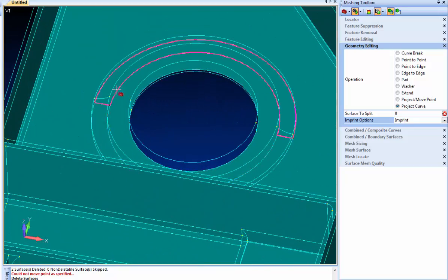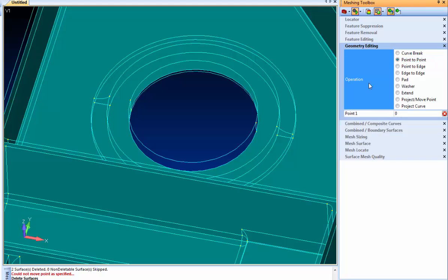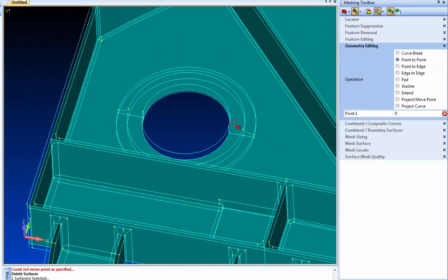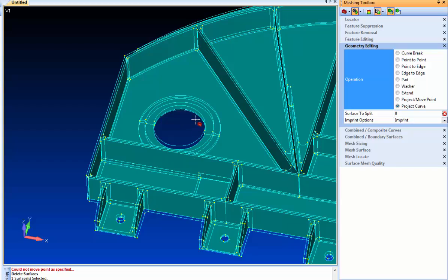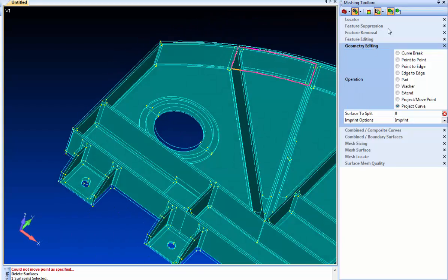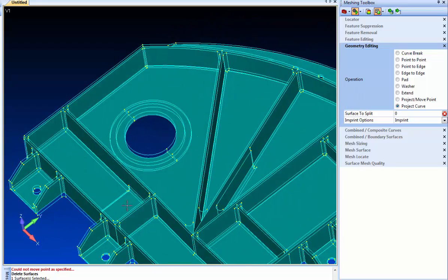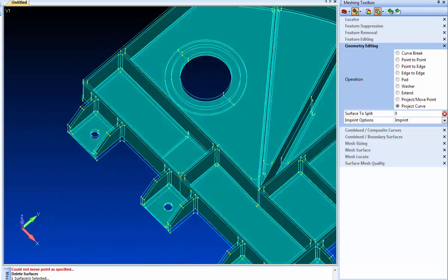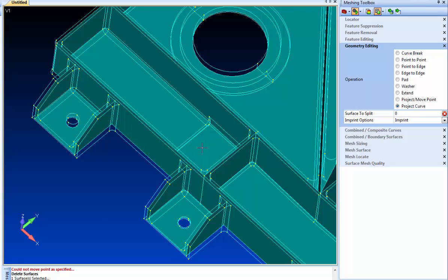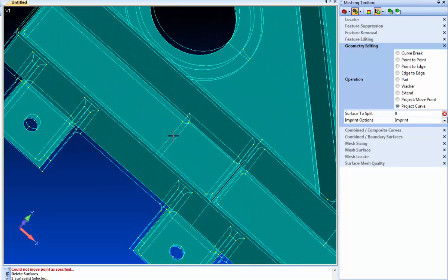And then when I really want to get into some map meshing, instead of having this circular annulus here, I'm going to use another split option we have in Femap and just split down in here. So now I'm going to be able to just play with the meshes later on. Now one other thing we need to do on this part, there are a couple of regions where there are thicker regions in these pockets that I definitely want to capture. So I need to kind of burn those splits in too into the mid surface.